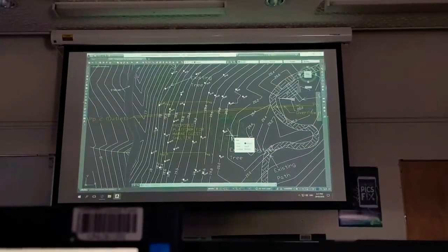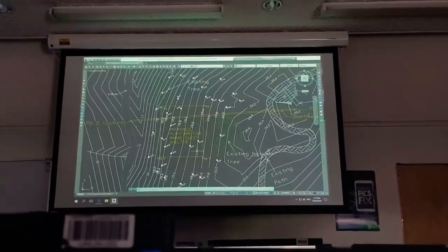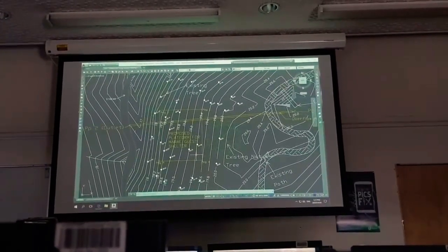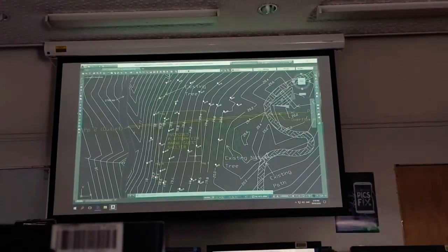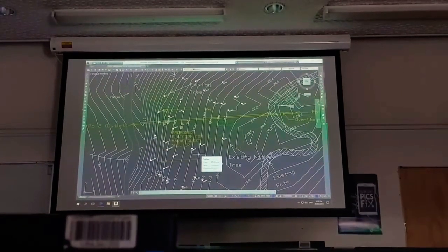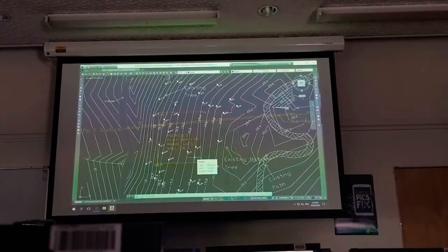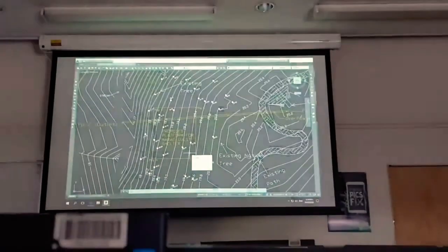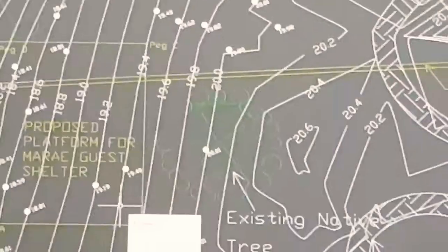And it does get rather cluttered, and these sections do make you think a little bit about how the pipe's going to look, what the outlet structure is going to look like, and why things are way up in the air. Some things are going to be way up in the air, others will be down quite low. It's not going to look right because of things in the background, etc. So the levels are going to be hard to calculate on the pipe because you're not taking the section along the pipeline. Where are we taking the section?